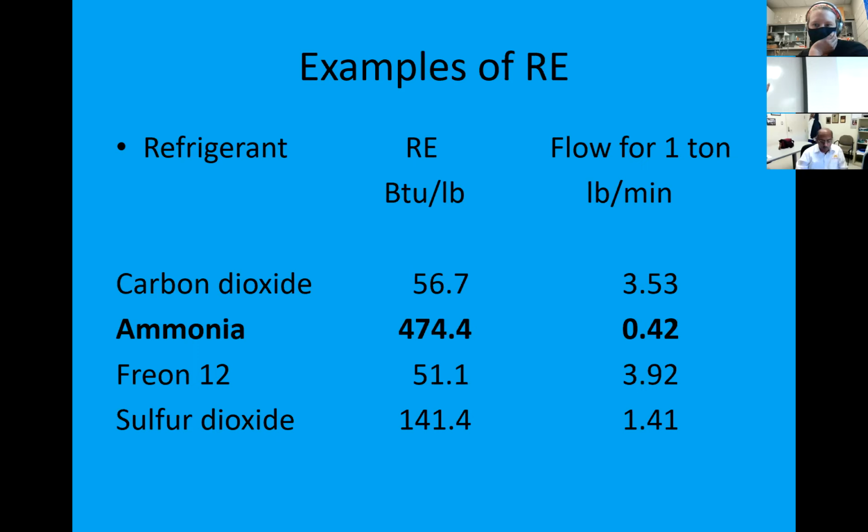And you may think, well, why isn't everything ammonia? It'd be great, except ammonia has a number of issues with it. You have to have a very, very tightly sealed system. Ammonia is toxic if you breathe it. Not to scare you too much, but there was an incident, maybe 40 years ago now, at a plant in Minnesota where someone was working on a freezer, and they opened it up, and they thought they had pumped out all the ammonia, took it in the face, and died. Basically, if you breathe ammonia, it'll burn out your lungs, burns out the alveoli.